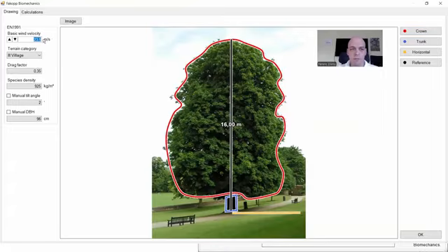Regarding the information on the right, we have the basic wind velocity. It is also called base wind in the Eurocode standard. This is not the design wind load. This is just the base wind that is defined by the standard for an area. The Eurocode EN 1991 standard is for structural engineers, but it has been adopted by arborists as well. So when you're looking for basic wind velocity, you need to consult your national annex, which has different base wind velocities depending on the region in which you are operating.